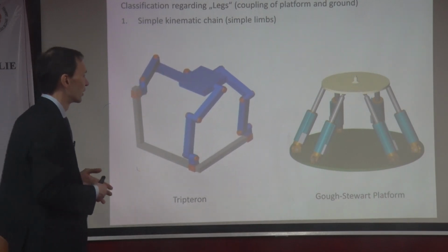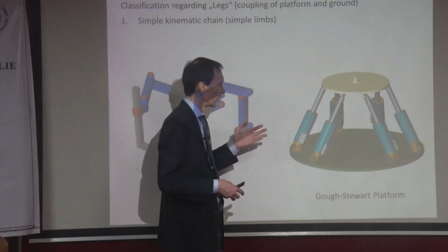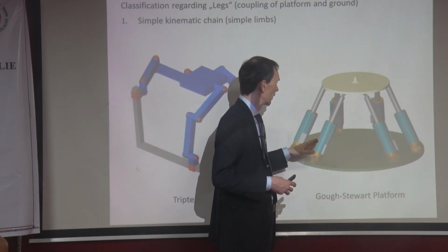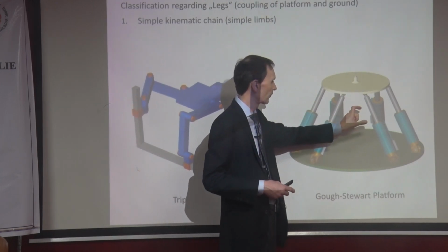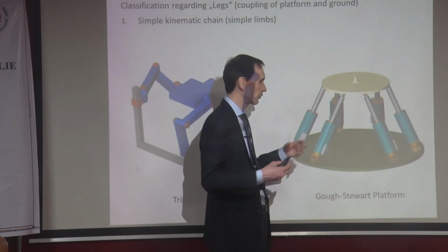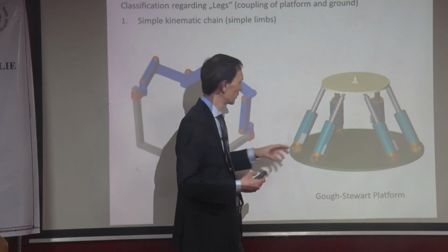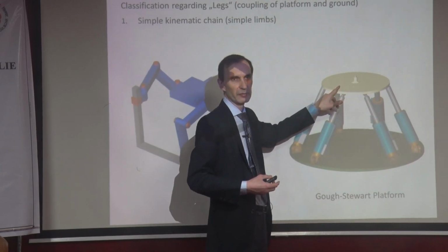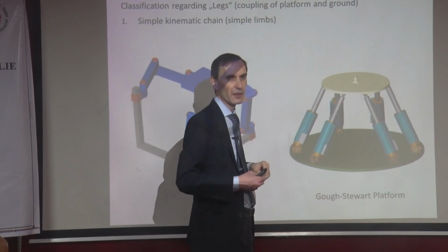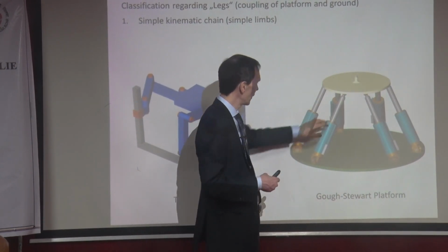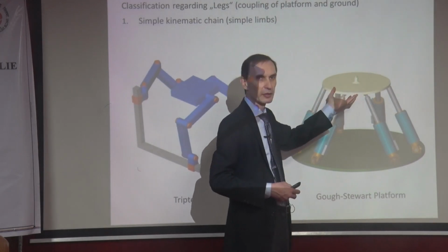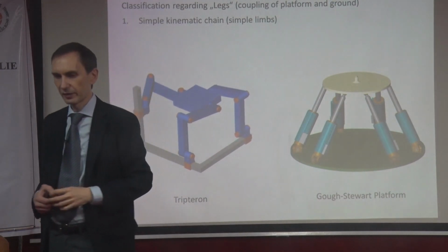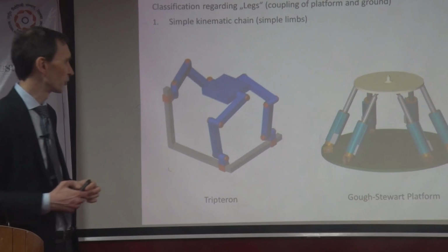For PKM, the forward kinematics is a problem. This is an old topic that people have been working on for more than 20 years. I give you the length of the actuators, which is what you have in your encoder and what you're controlling. Now, if you have the lengths, how do you get the platform configuration? For the same lengths, the platform can, for example, be swapped over. It's not unique, and that's a bit of a headache. But there are ways of doing it.